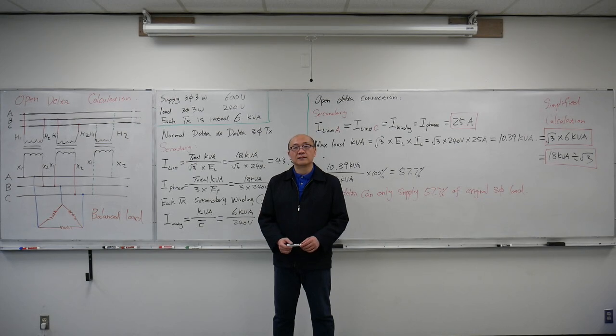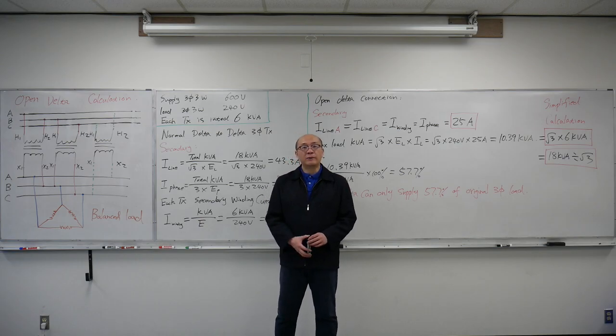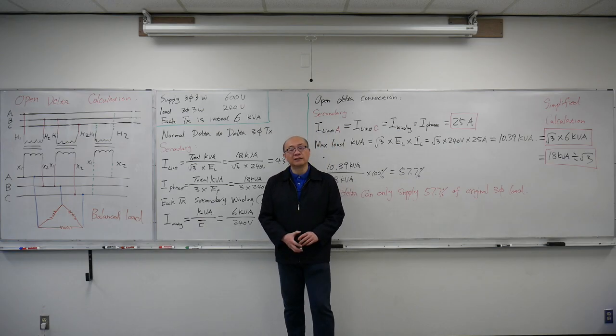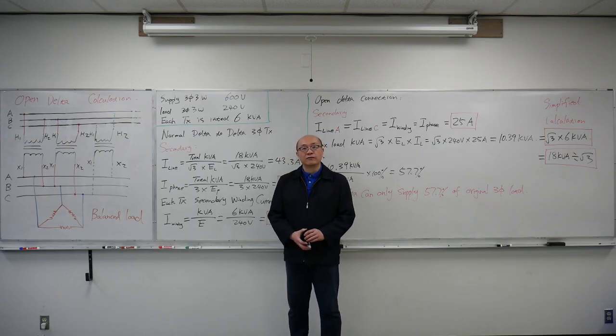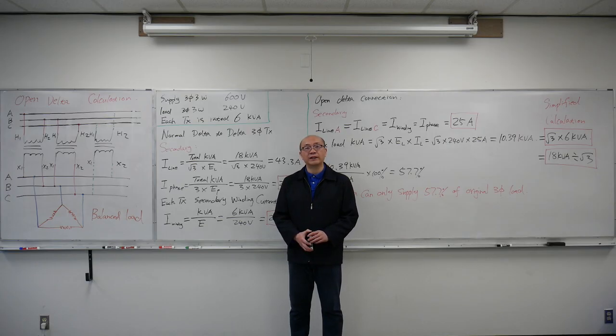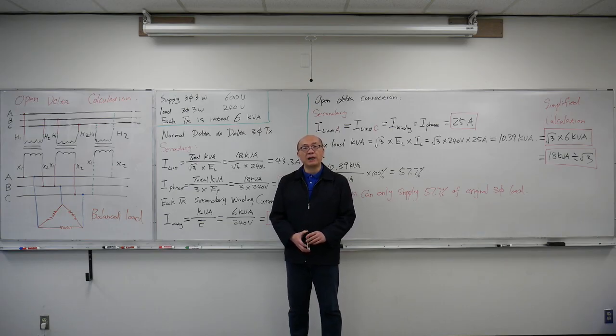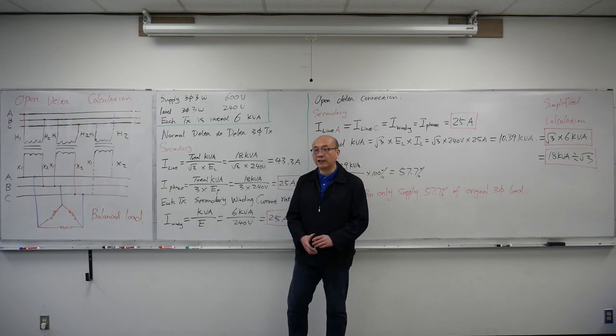Hello everyone. In this lesson we're going to talk about open delta calculations. If you remember, before we talked about open delta, we said that with three single-phase transformers, we build a three-phase transformer bank. One advantage is that if one of the transformers breaks down, we can still use the other two transformers to supply the three-phase load. This is the case with open delta.